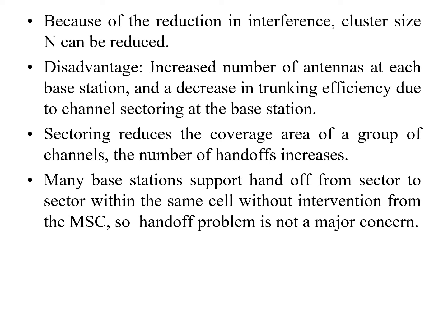Disadvantage: increased number of antennas at every base station and a decrease in the trunking efficiency due to channel sectoring at the base station. Sectoring reduces the coverage area of a group of channels. The number of handoffs increases. Many base stations support handoff from sector to sector within the same cell without intervention from the MSC. So the handoff problem is not a major concern.